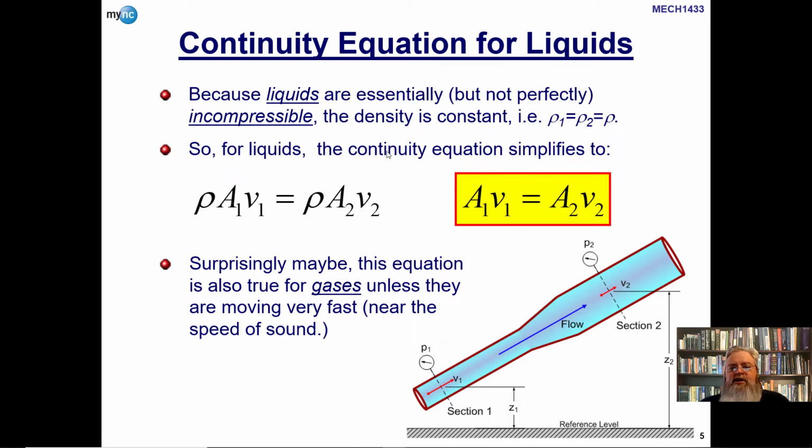In lots of applications, the slightly incorrect statement that liquids are incompressible is close enough to being true that it's really useful. So we often apply it. And we save the compressibility of fluids for high pressure change situations where the small change in volume is going to be significant and needs to be accounted for.